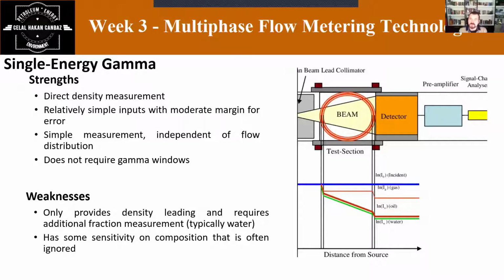It uses a nuclear source, and from this nuclear source, the gamma ray photons pass through to your line. As I mentioned, it becomes part of your line, right? Your flow is coming directly, and these gamma ray photons pass across the cross section as a line, and what happens? It collides with the molecules of your flow, and according to that, it gives you a result.